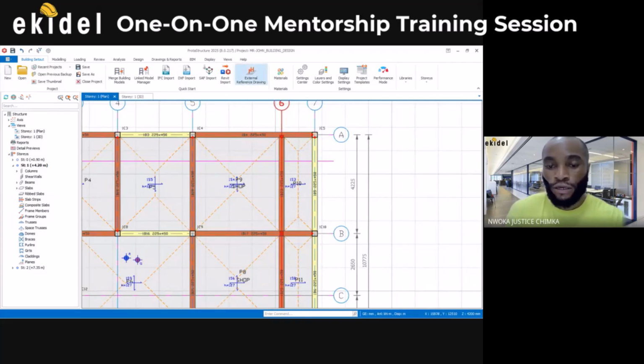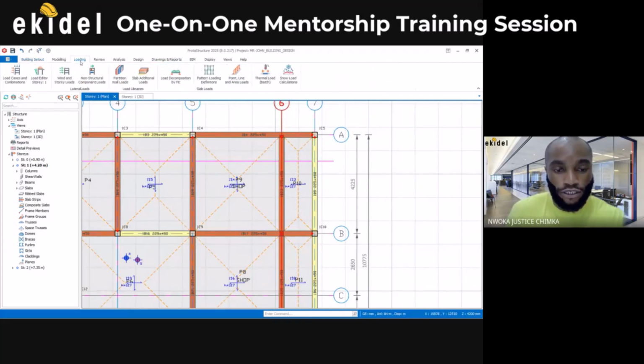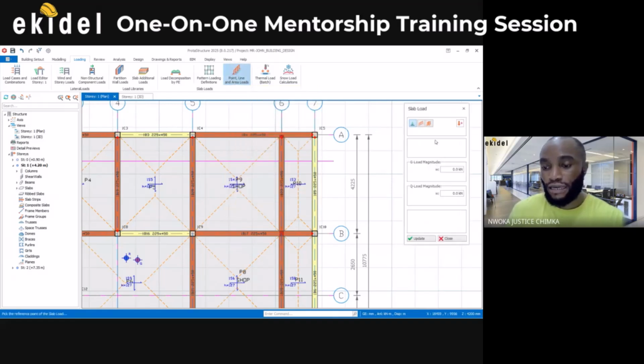So I'll come back to loading now. Loading here, and then click on this here. Then click on line load here, this icon here. Let me say the load of the handrail is not that much. I can choose 1.5 or 2.0.